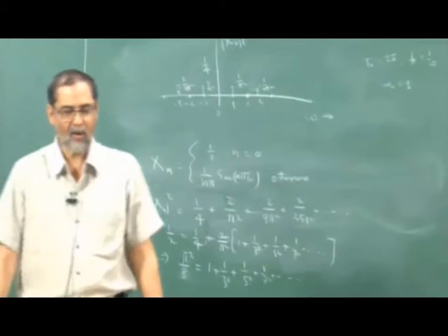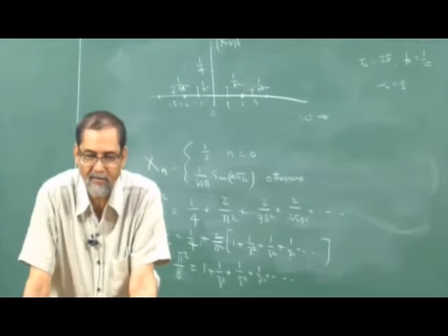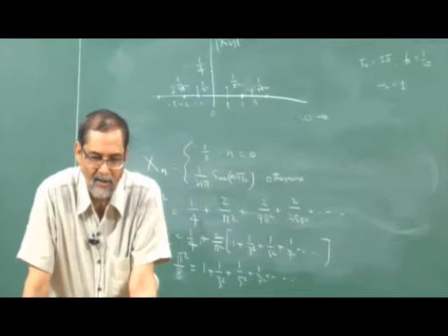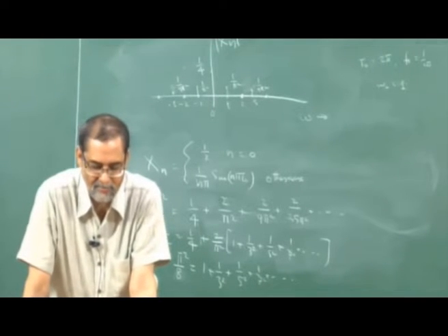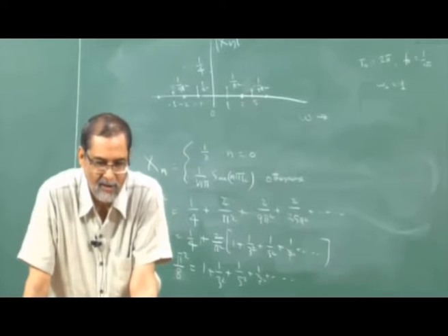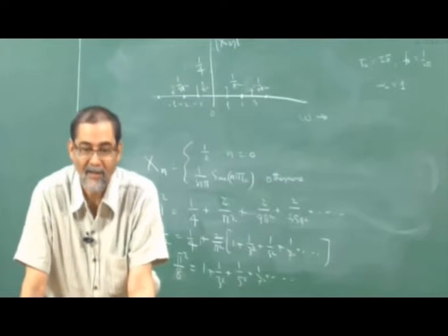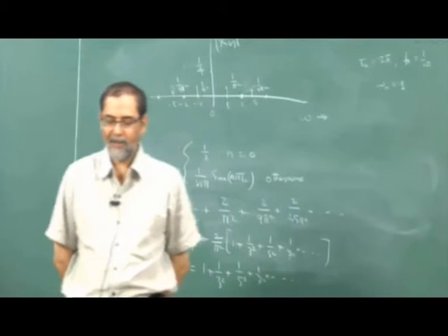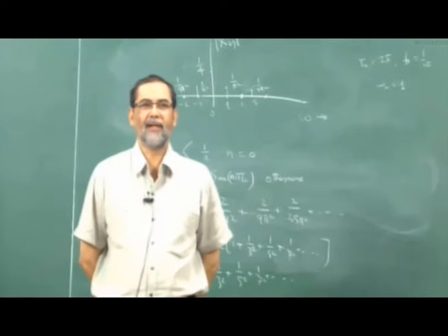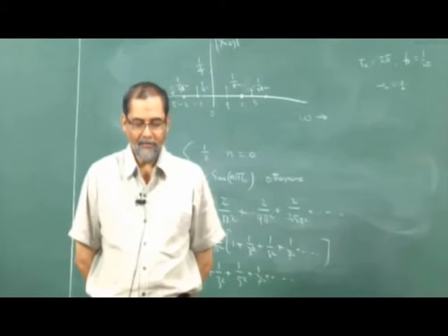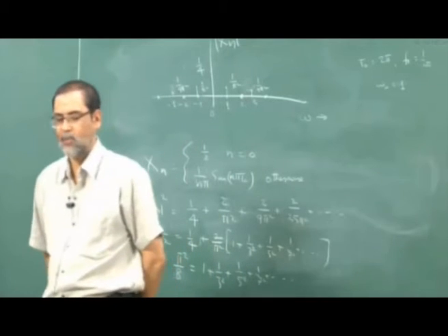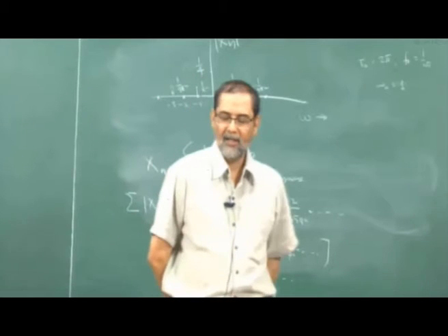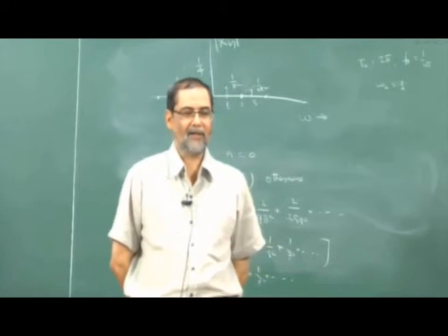I said you cannot convolve two infinitely long power signals, right? Because convolution of course is an integration, and that integration does not exist. So only when that integration exists. Remember, before you do anything, if you are dealing with integrations where the limits are plus or minus infinity, you have to take a pause, right? These are not normal integrations.